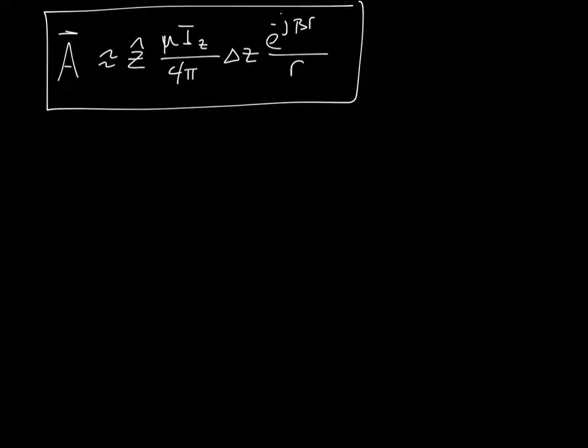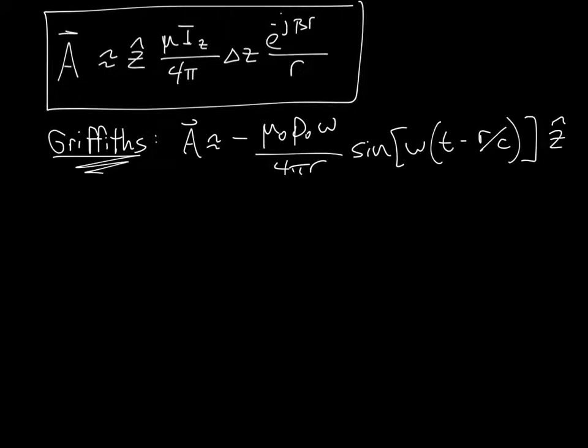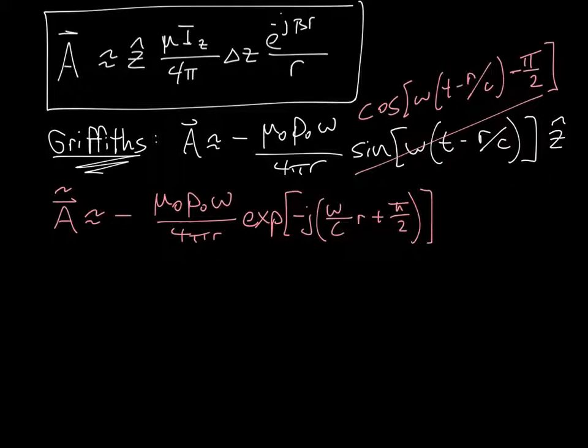This vector potential formulation was derived following 3 antenna engineering books and cross-checking against optics books, as well as pure physics theory books. The antenna engineering books particularly were useful: Balanis, Stutzman, and Krauss. And when cross-checking against such as Griffith's E&M, these vector potentials are essentially identical once I make some simple modifications to Griffith's formulation.